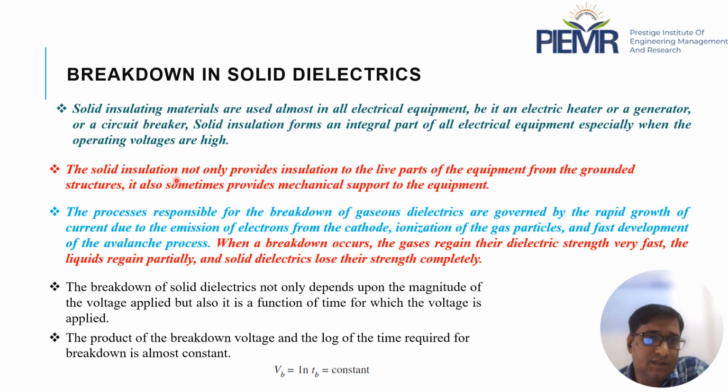Solid insulation not only provides insulation of the live parts of the equipment from the grounded structure, it also sometimes provides mechanical support to the equipment. Means it serves two purposes. One is insulation, the other is that it can provide mechanical strength to the equipment.